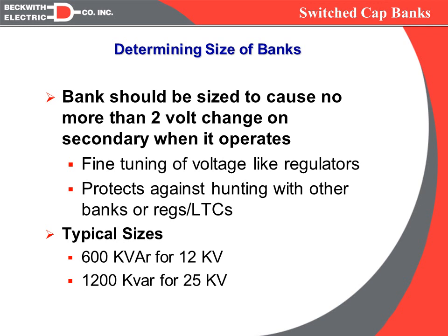One thing that we've got to do to meet that goal is make sure that if a cap bank operates, the effect it has on the secondary voltage will not be great enough to force a regulator or an LTC out of band. So for instance, if I close in a cap bank control and it affects the secondary voltage by 4 volts, that may induce the regulator or LTC upstream to have to go in the opposite direction to eliminate some of that voltage increase. So as a typical rule of thumb, we'd like to see the effect of any bank be less than 2 volts.